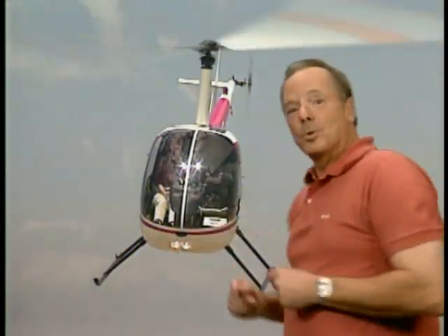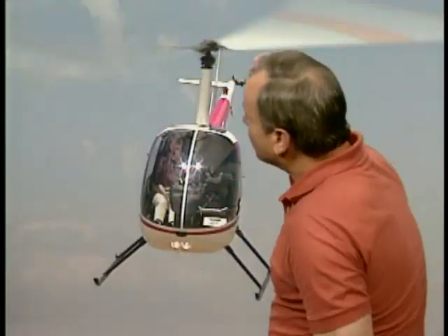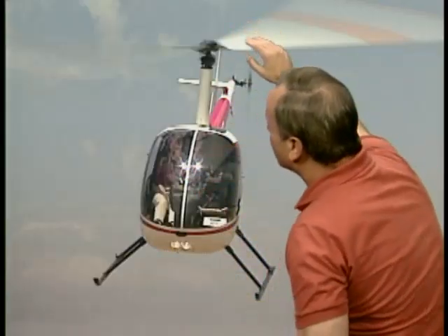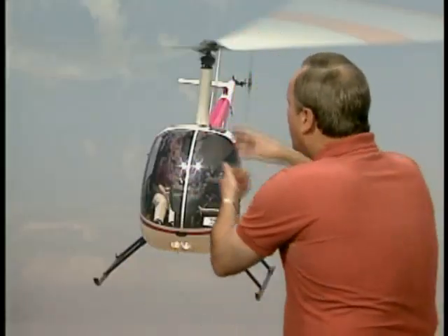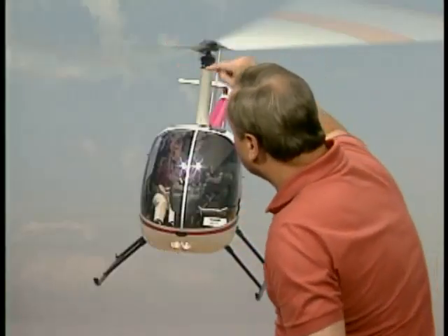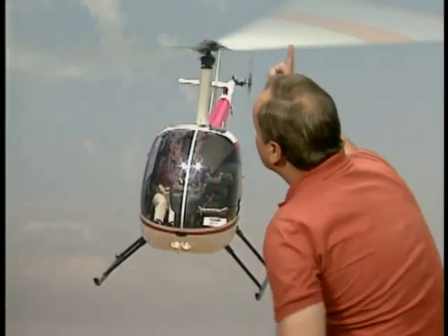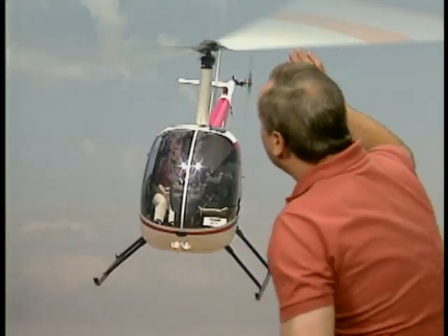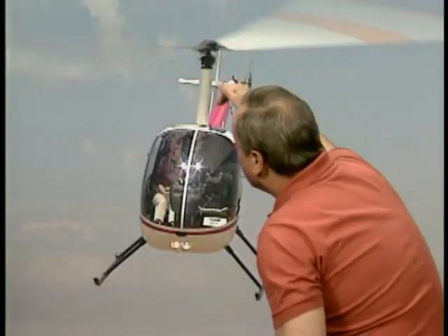Now, let's take a look at a couple helicopter components they want you as a mechanic to know about. As you know, the way a helicopter works is the engine is driving this main rotor up here. So it is a very good idea to have the engine connected to the main rotor. But if that engine should quit or slow down so that it's no longer driving the main rotor, it's not such a good idea to have the main rotor connected to the engine, because the engine is now slowing down the main rotor. In the event of an engine failure, it's very important to maintain rotor RPM, so you don't want the engine slowing it down, so therefore there is a solution.